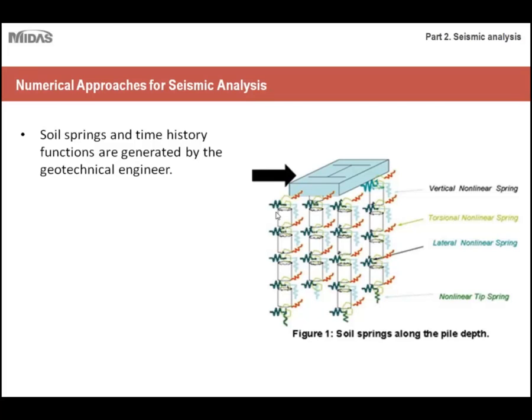For example, just imagine a bed spring pushed up against a cinder block or a tube. If you were to apply a force to it, that spring would oscillate. Just try to imagine it that way. That's why they're called springs. These spring elements take into account the oscillating behavior of how, when you apply a seismic load to this pile foundation, it's going to shake back and forth. So these soil springs would take into account that type of behavior.